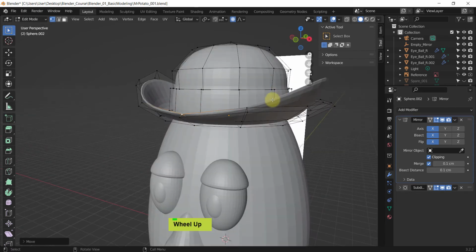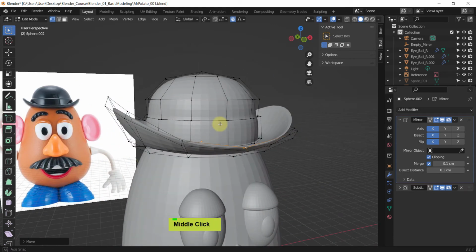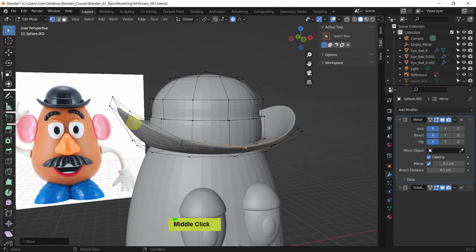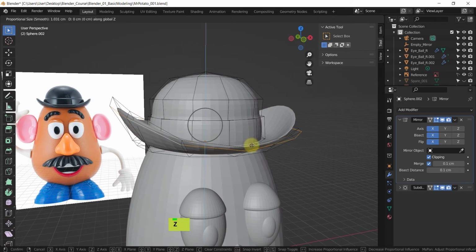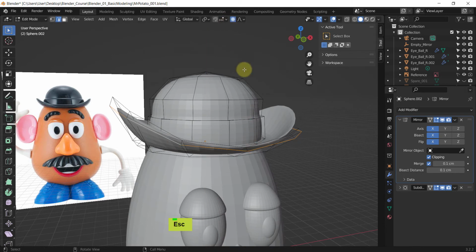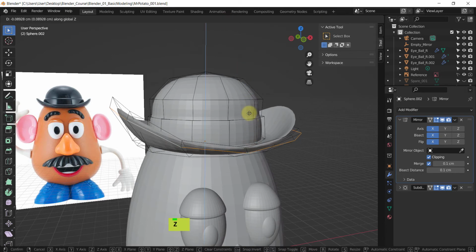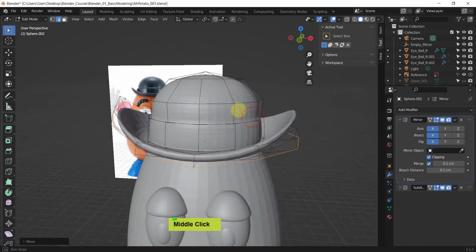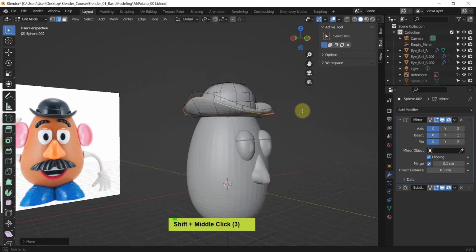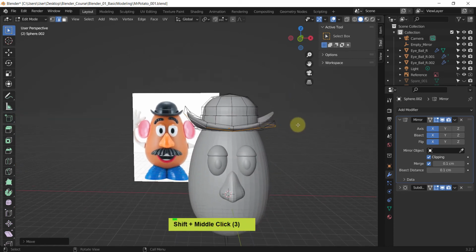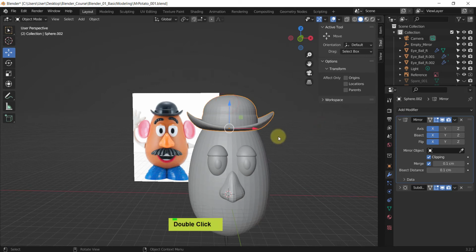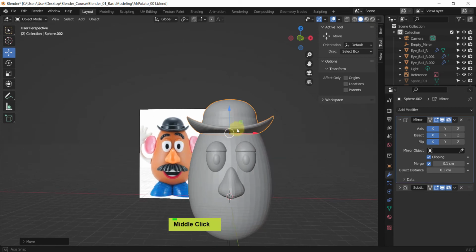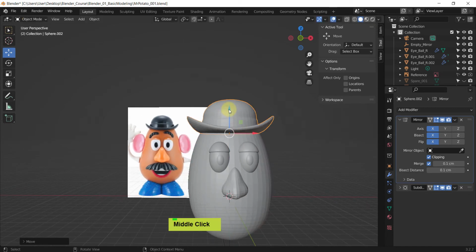Alright, nice. If we want to make the edges a little bit thicker, we can also select the running edge, so edge mode, Alt and G, and drag up, turning off the proportional editing, G, and on the y-axis, so we can change the thickness of it. So I will just add back a little bit of thickness. Alright, that's fine for now, for me. And maybe pulling this in a little bit more to sit more in the head. That's fine. Alright, now how to do the eyebrows.